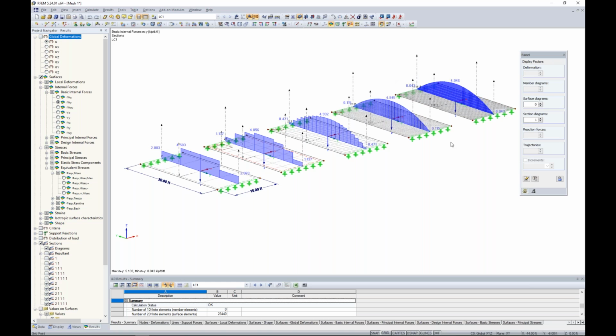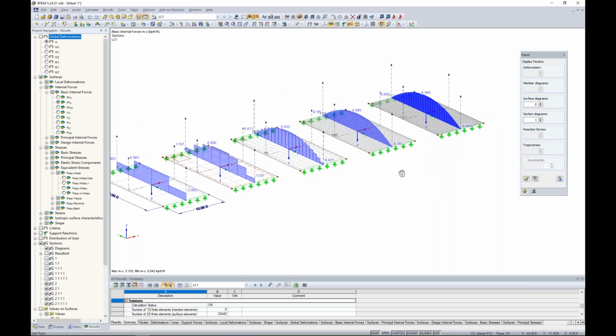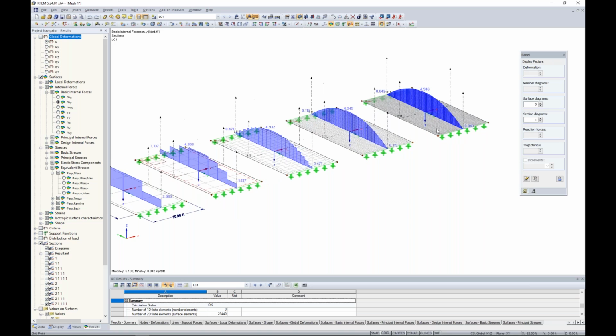4.946. So at some point, our cost to benefit ratio, so to speak, where we're continually refining this FE mesh is really not drastically influencing our results. For example, these two elements here: the one on the left has about a third of the FE mesh that the one on the right does, yet our results are only changing by 0.001. So it's this happy medium, finding the right balance of when we can refine our FE mesh to gain accurate results, but not so much that our calculation time increases significantly because we've added all these additional elements.